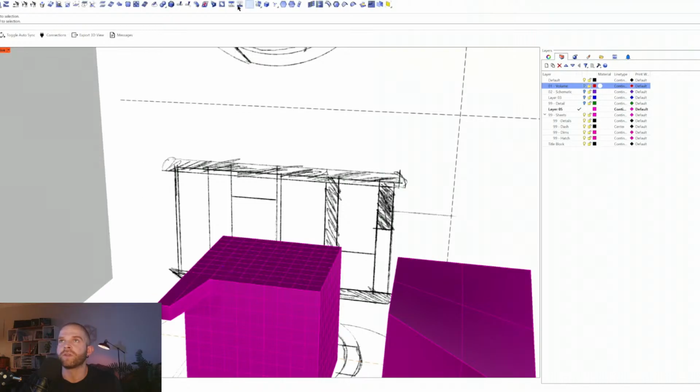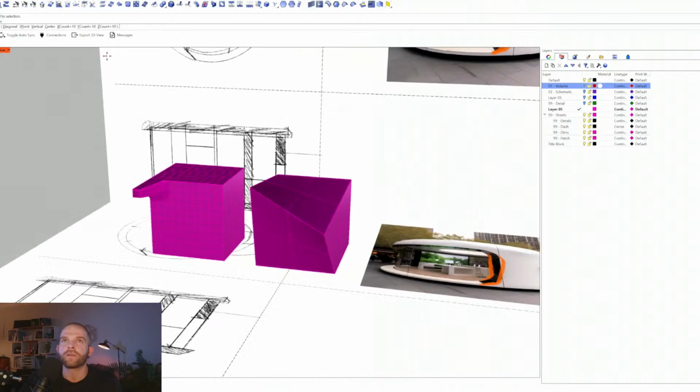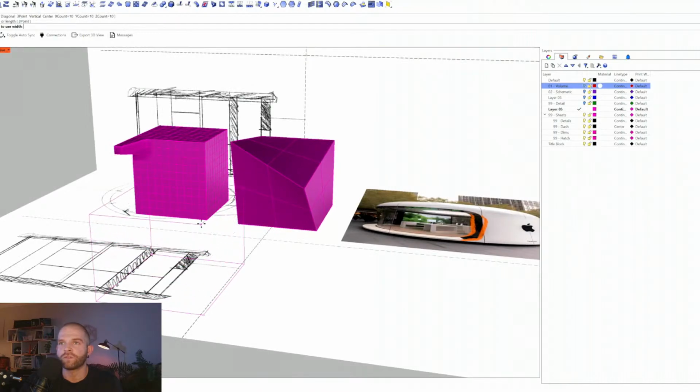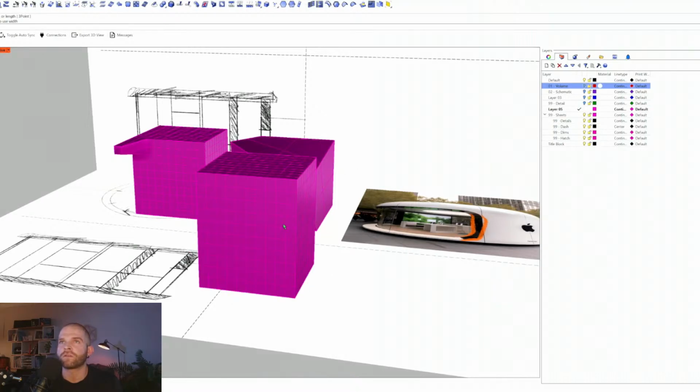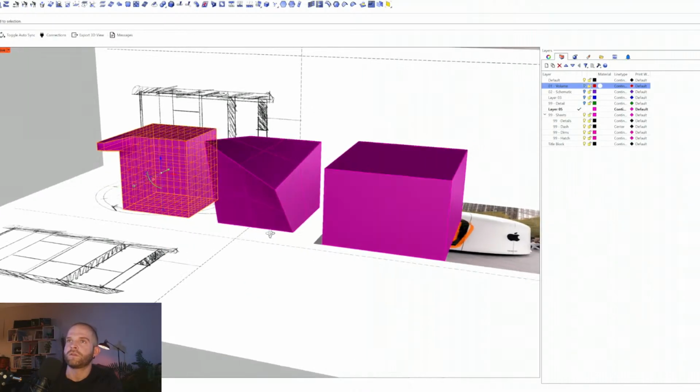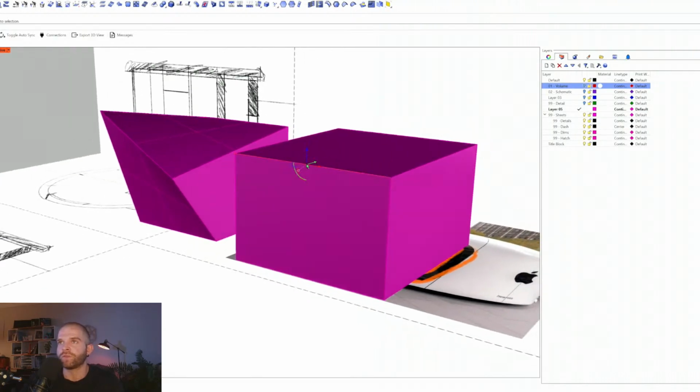That's a little bit different, because if I were to select this whole row, or let's say I build out a mesh cube that is just one face. So I start to do a cube, and before, let's try that again. Okay. So before we draw it, we actually have to change the count. So X count, Y count, Z count. For X, we'll just do 1, and Y as well, and Z as well. So we'll get a mesh box here that is more similar in topology to our cube. If we grab this edge and we move it along, it's a similar effect.